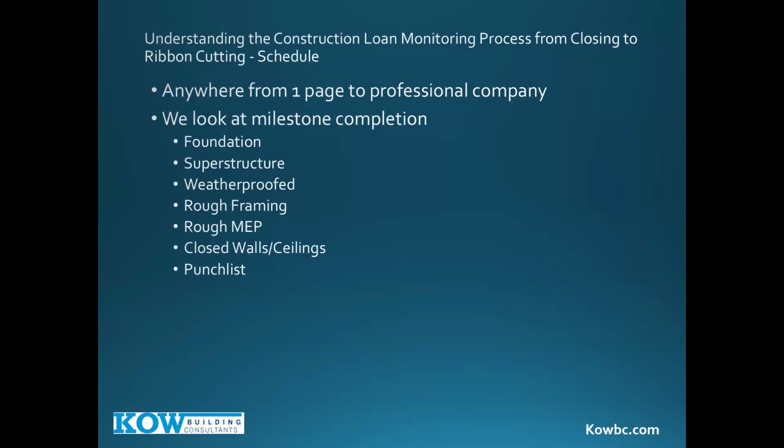Really good. Very happy. Well, let's have a top out party because that's a really, really good moment for the project. Okay, we're weatherproof. Okay, we can now work inside. We can put salamanders in there, bring in heat. We can rock and roll inside with lots of stuff like rough framing. Now rough framing's done. Oh, that's good. Rough MEP's done. Okay, now we're really cooking. Closing up walls and ceilings and punch list. So milestones are very key for us because they're really good indicators of where we're moving from one phase to another.